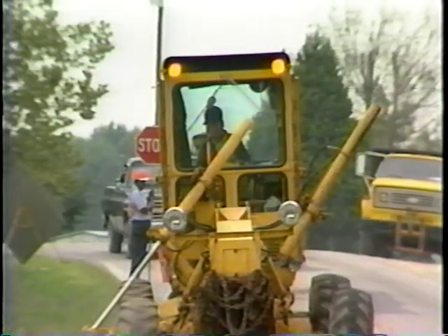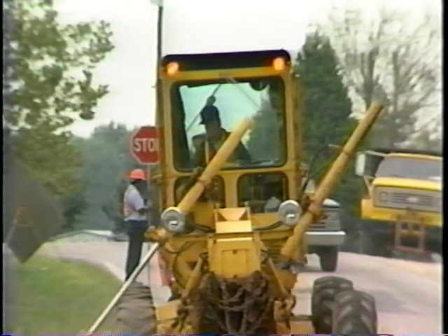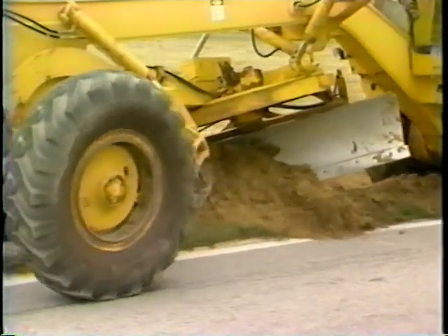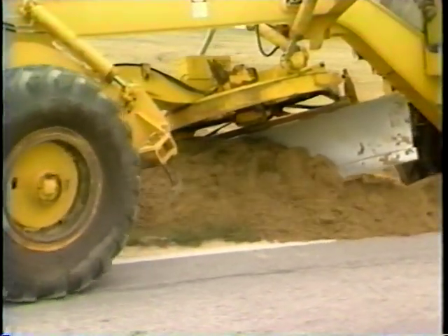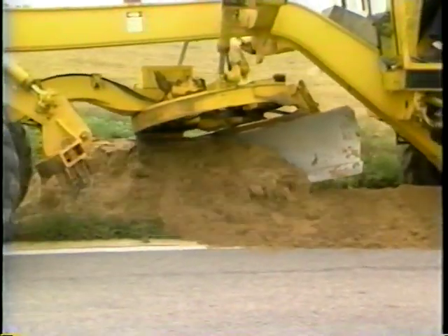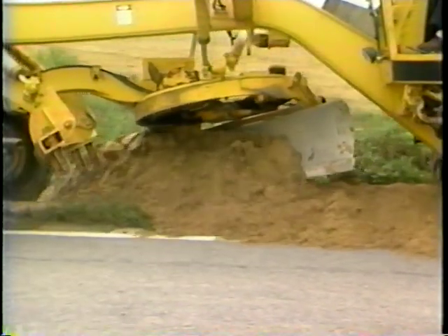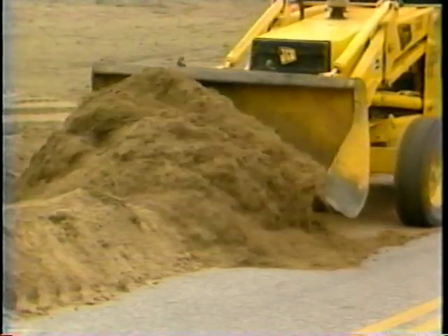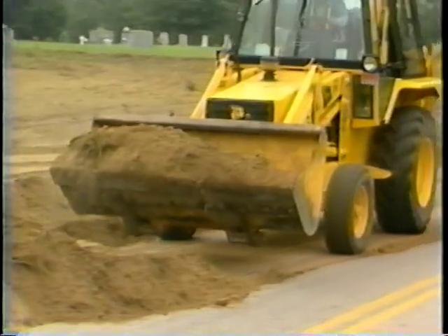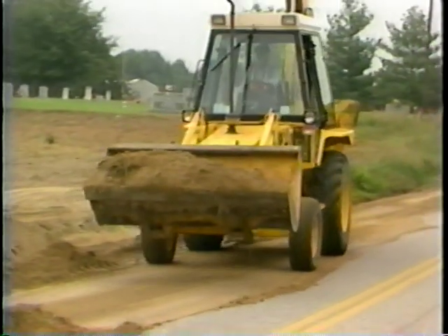One thing to be considered prior to this operation is the location of additional material. Possibly, material can be recovered from ditch maintenance performed in conjunction with the shoulder repair. Ditch maintenance or high shoulder repair performed on a nearby roadway can provide excess material.